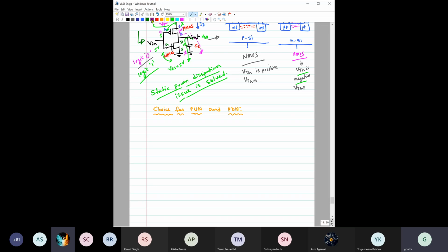Okay, here, this is interesting. Yeah, Shubhayan, very good that you thought in that way. Okay, so say we are using an NMOS as the pull-up network. We have used VDD here, and this is basically Vin. It is expected we have something below, which as of now we do not know. It is the pull-down network, and maybe it is controlling the pull-down network, but we do not know what the pull-down network is as of now, right?